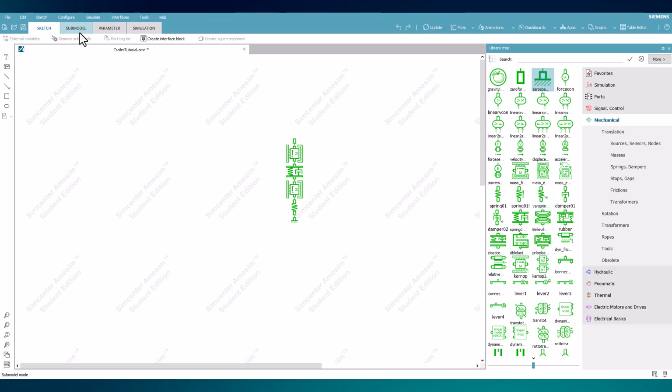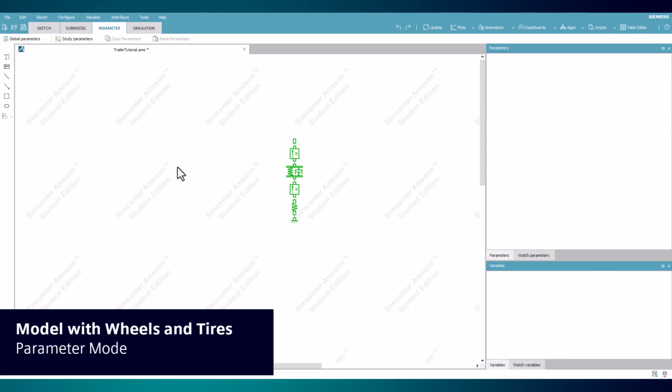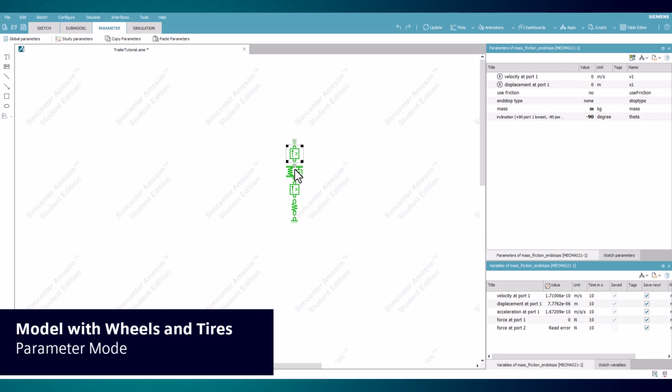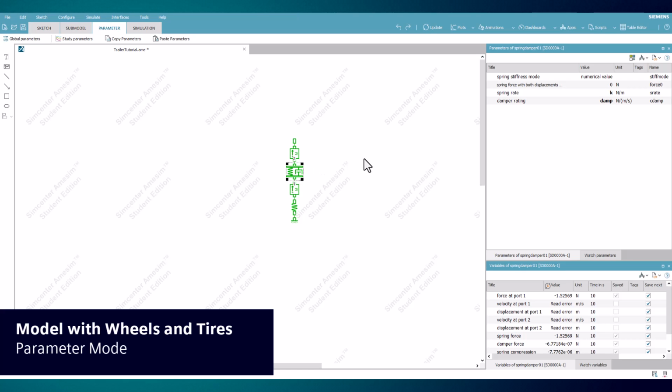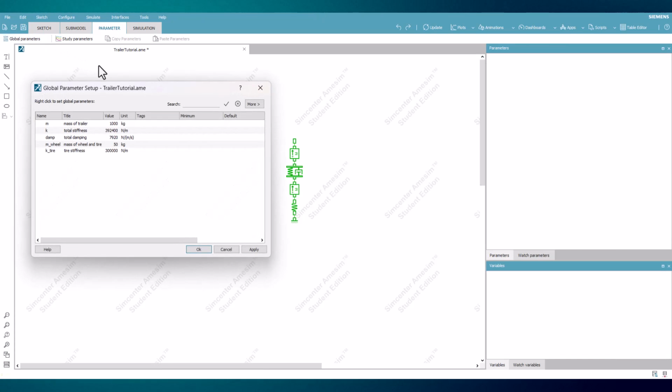This model is built to combine the properties of the two suspensions, wheels, and tires to create a two-body dynamics problem. Moving to submodel mode, Premiere Submodel is acceptable. The parameters for the top mass and the spring and damper components will be the same as what was done for the model with a combined suspension, using the global parameters whose values were determined in parts 1 and 2.